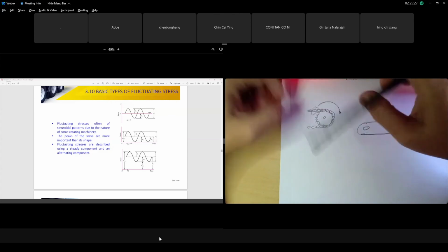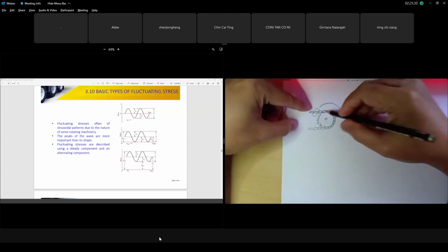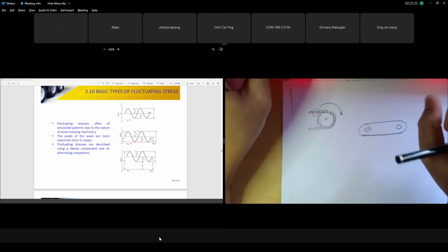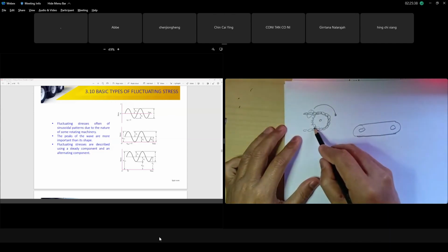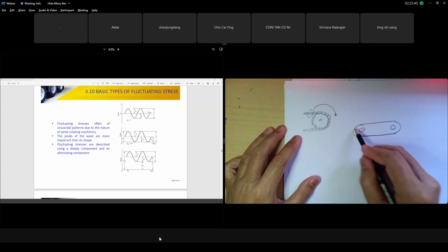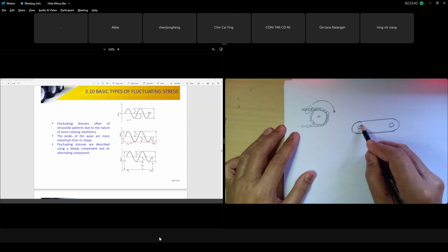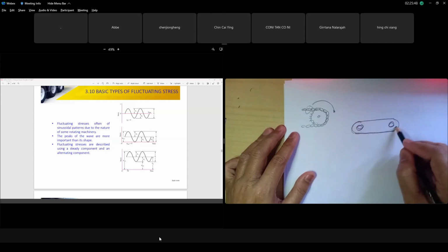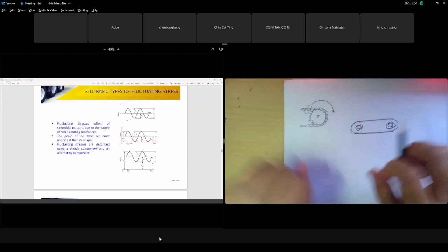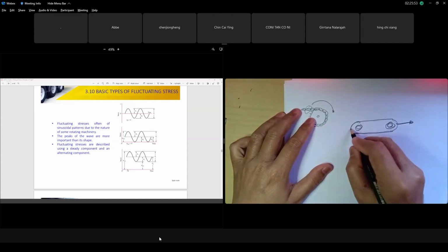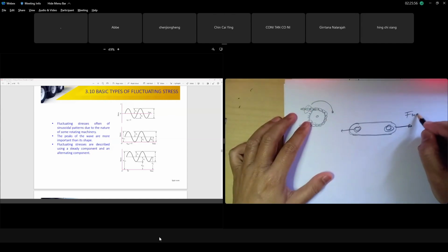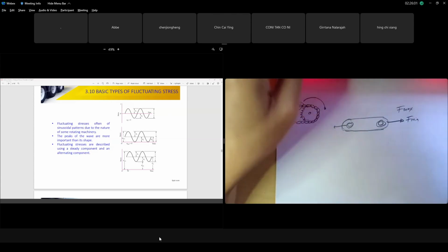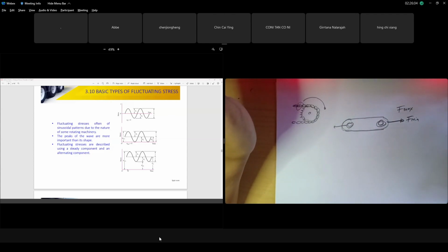So you are the engineer of that company. You can calculate whether your chain is strong, because when it is mounted on the bicycle and the cyclist pedals fully, all the chain links are the same. If we take one component of the chain, it is like this. This is a pin, this is the chain, and the metal plate is like this. When it is full cycle, it has tension between chain and chain. So it has F maximum, and when it's not full cycle, it has F minimum. This is what we call fatigue loading. This is another case.